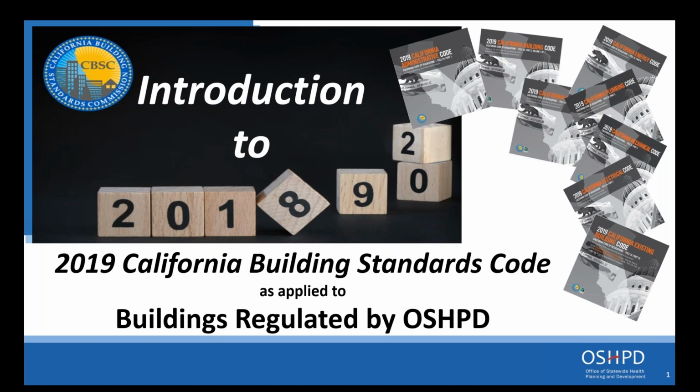And so I'm definitely open for that. The one exception I would certainly take to that would be anytime you have a med gas type system. If you look at NFPA 99, there is zero mention of automatic valves for class 1 med gas. And the reason for that is if one malfunctions, people die. So other than that, I'm definitely open to automatic valves. We have a lot of good, smart designers out there that I think can certainly integrate these things in fine. We'll be open to suggestions on that.